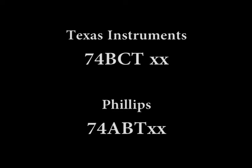The 74 BiCMOS series. The 74 BiCMOS series of devices incorporates the best features of bipolar and CMOS technology together in one package. The overall effect is an extremely high speed, low power digital logic family. This product line is especially well suited for, and is mostly limited to, microprocessor bus interface logic. Each manufacturer uses a different suffix to identify its BiCMOS line. For example, Texas Instruments uses 74BCT, while Signetics Philips uses 74ABT.